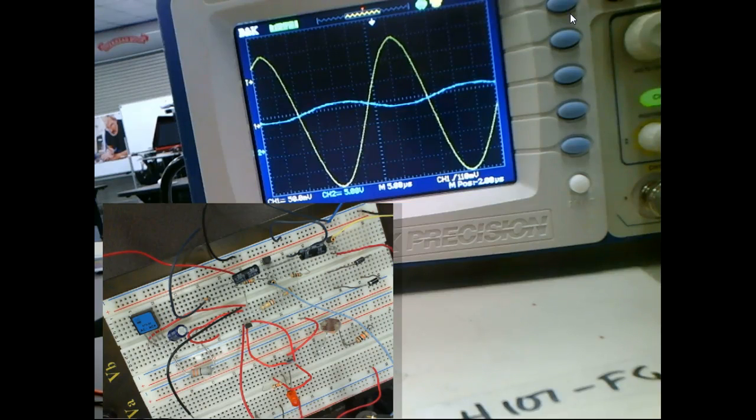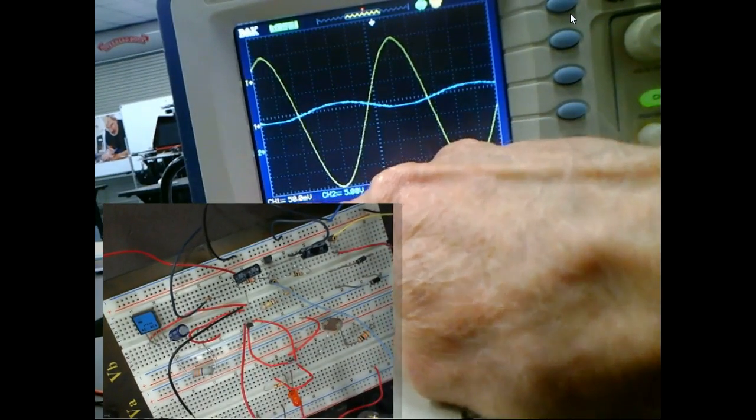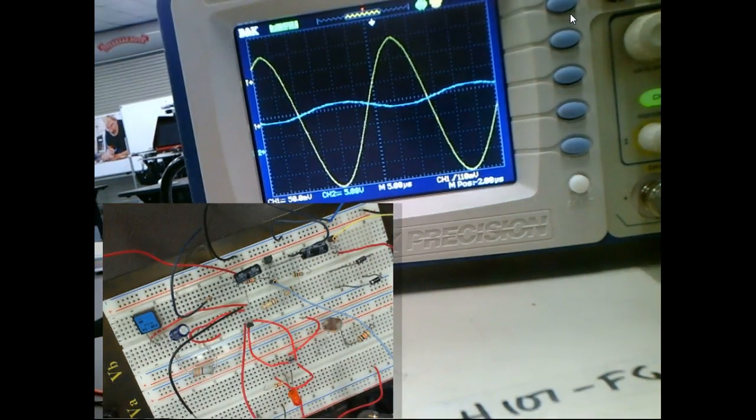What we got? Yeah, 50 millivolts per division. I don't know if y'all can see that or not. There it is right there. Well, your scope measures peak to peak, so that's what we're calibrating, peak to peak. We're not worried about RMS because I'm going to use my scope to measure peak to peak out, right? You understand? So what we got, our input voltage? 7 times 50 millivolts. 350 millivolts in.